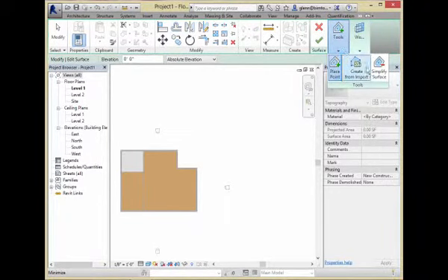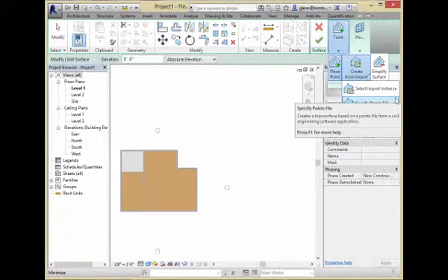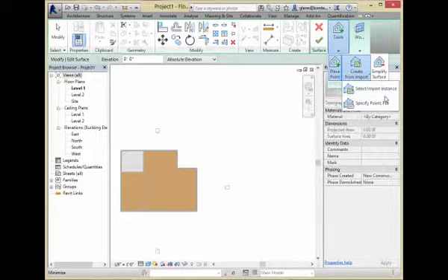And from importing, you have the choice of either going to a points file, which a surveyor may have given you. It's just a bunch of XYZ points. Or from an import instance. So where I'm not going tonight is, if you go to Google Earth, find some piece of ground, and export the topography as a DWG file, it's really just giving us XYZ points. We grab those points from Google Earth and bring them in here, and we can then convert that into topo surfaces. So another time I'll show you how you actually do that for your custom site.